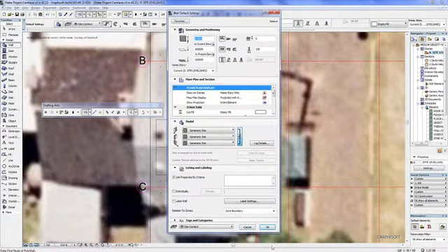Now let's draw that wall. So what we want to do is go to wall tool. All the settings are just as they were. Now to get the offset, we need to go to here, offset constraint. And so you know that the offset constraint is active because the cursor has that little offset icon that's following it around. So remember, draw the wall in an anti-clockwise method. Okay.